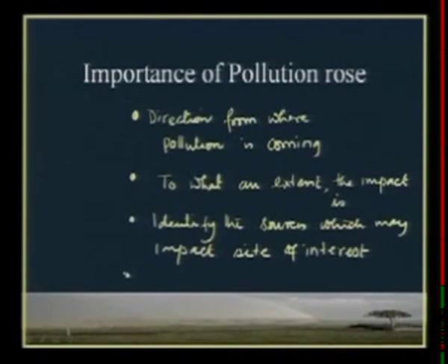and you can even plan a pollution control which can be season specific, because you see the wind direction changes from season to season, and so will the impact of sources. In winter, most of the pollutants may come from the north, and in another season it may come from the east. So, you can say, well, all right, when it is summer, the pollution sources that must be controlled are those generating pollutants from the south. This way you can make very useful decisions and contribute to pollution control.